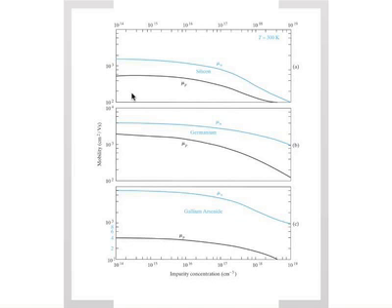Let me just reiterate this point. So you see the mobility. If you increase the concentration of impurities, let's say you dope the silicon from 10 raised to 14 per centimeter cube to 10 raised to 19 per centimeter cube. That's 5 orders, and that's very typical. That's not very huge or anything like that. It's very standard. You can see the mobility drops by several orders of magnitude.